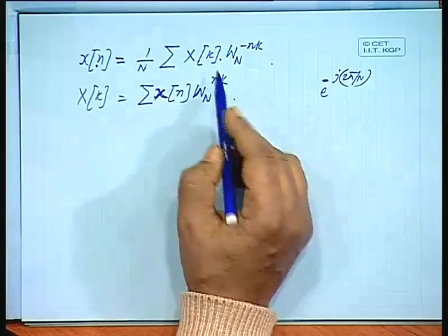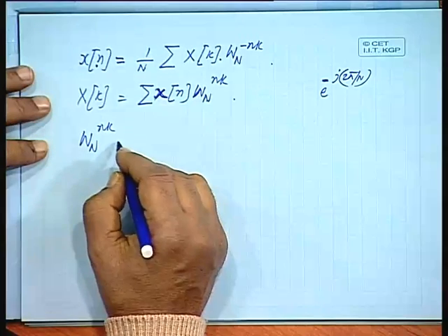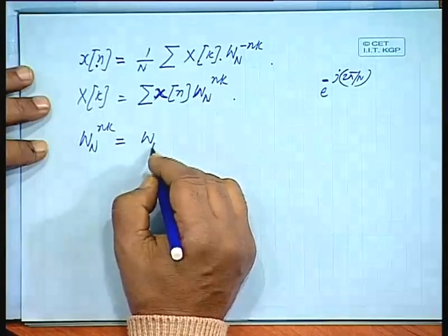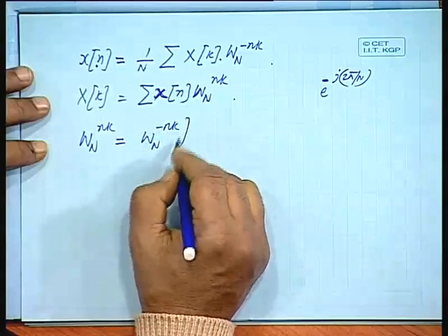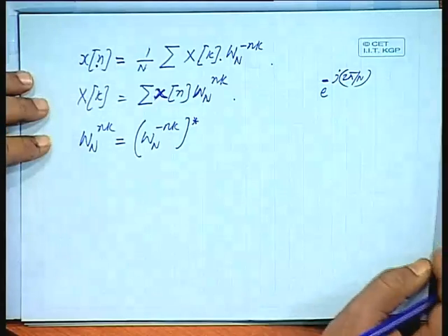Earlier, for the continuous domain, you were integrating from minus π to plus π. Here you do not have to do that. You just take the summation of those 8 points and multiply by just the complex conjugate. Earlier it was minus π/4, now if I put a power of plus 1, it will be plus π/4. So it will be just the complex conjugate. So W_N^(nk) is nothing but the conjugate of W_N^(-nk). It is just a complex operator.